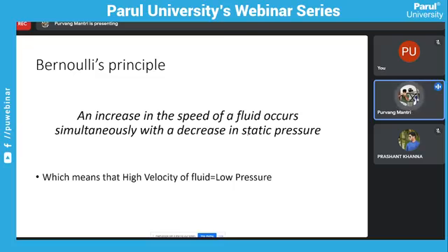with that reduced cross sectional area, the pressure is dropping at that particular point, and because of the low pressure over there, the water attains high velocity, not exactly way too high, but relative to the actual velocity of the water, it will have increased velocity, and it will move further ahead, and it will have an impact on the body surface, so that the dirt and the grime can be removed off the surface of the body.